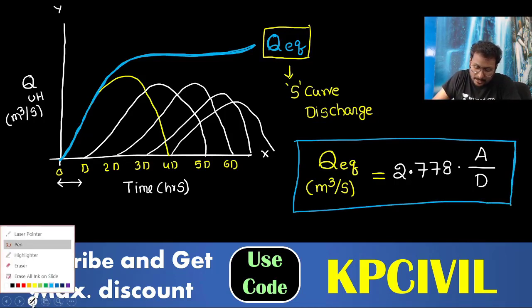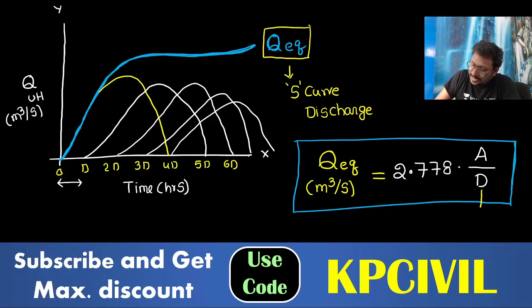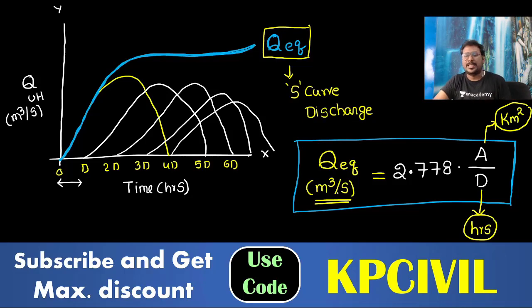D is the duration of rainfall occurred, considered in hours. Remember, you must take D in hours only, and area of catchment in kilometer square only. Then you will get a discharge in meter cube per second.